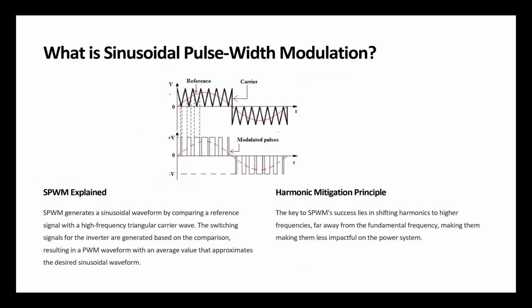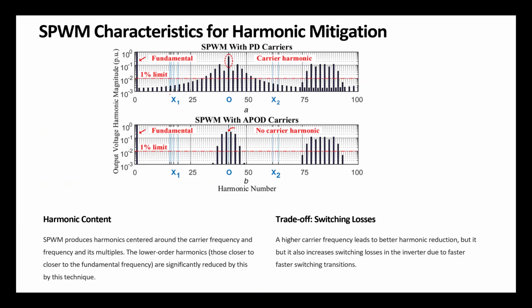Okay. So based on that, we already know we have SPWM techniques. The first option was to create or optimize a switching technique, SPWM. We already know what SPWM is. We already talked about that. And we wanted to just use the degree of freedom that we have in the SPWM in order to decrease the harmonics.